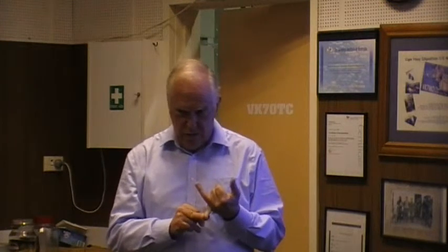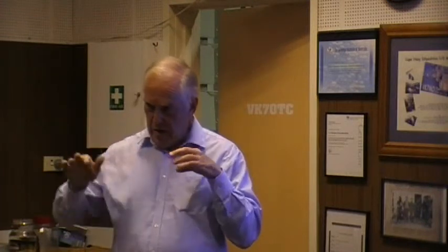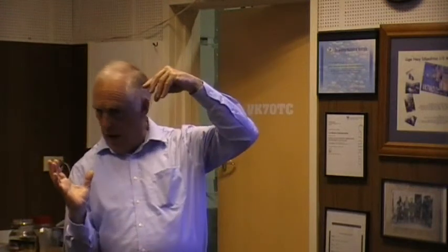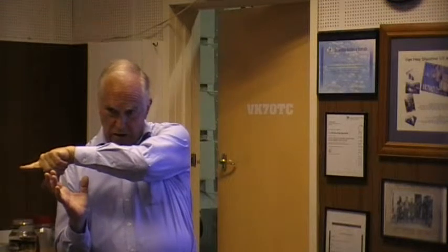So it's down to the performance of the devices in the low noise amplifier and everything after that, but hopefully you swamp that with lots of gain in the low noise amplifier, and the spillover, particularly the spillover of the feed to the dish. If it's seeing anything outside the dish and you're pointing up there, you're going to be seeing the ground behind the dish.